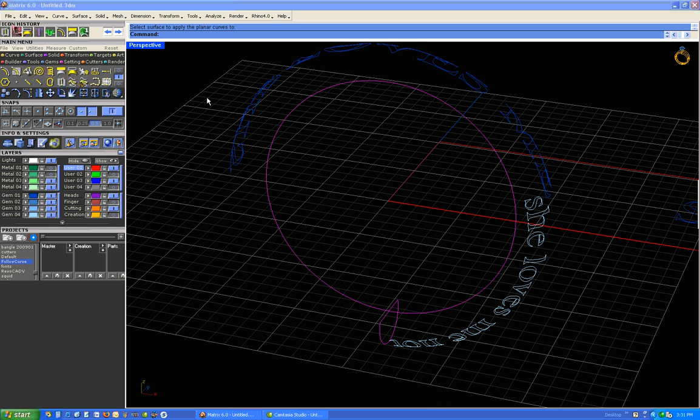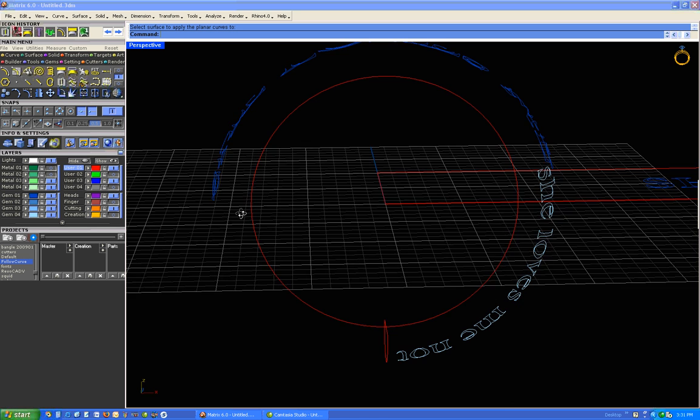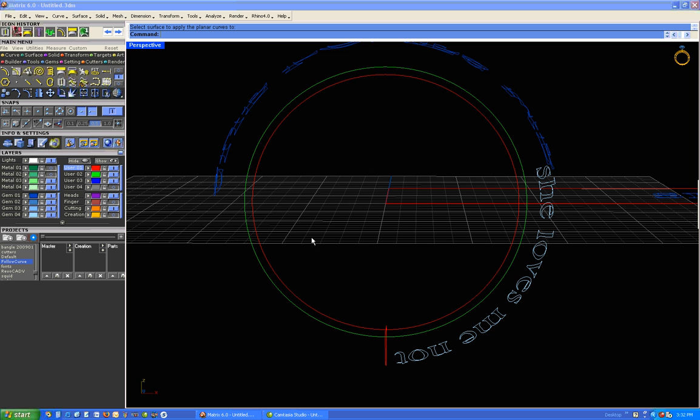Another way to control where the curves go on the surface of your ring model is to split the surface of the ring and extract only that portion of the ring that will have curves. For the model we have been using, a simple method is to draw a circle using F4 or to offset the ring rail curve, which is what I did here.